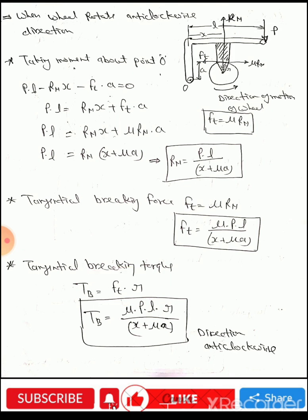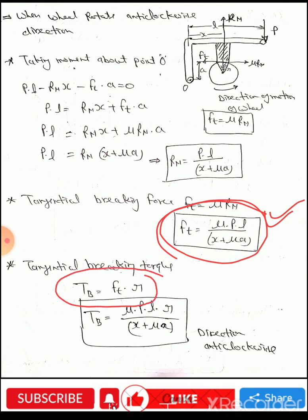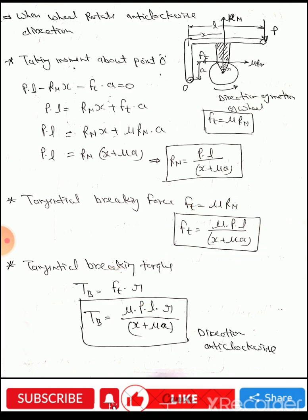Putting the value of Ft, the tangential braking force, from here into the tangential braking torque equation, we obtain the tangential braking torque TB equal to mu P L into r upon x plus mu A.